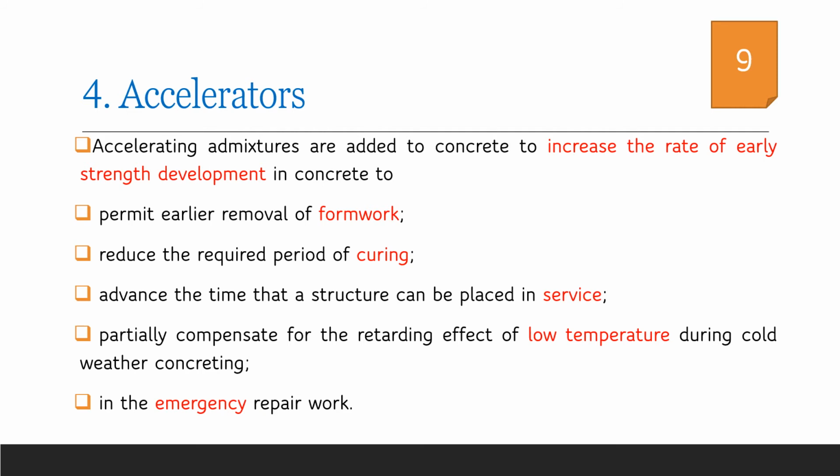Also, in areas of cold weather, due to the low temperature around the concrete, there is a chance that the setting happens at a slow rate. In that case, accelerators can increase the strength gain speed. Also, when we are thinking about doing emergency repair works, accelerators can help in gaining strength at a faster rate.